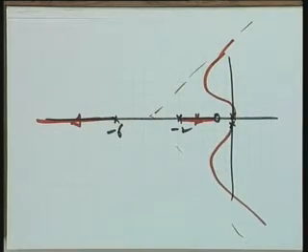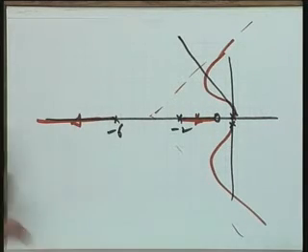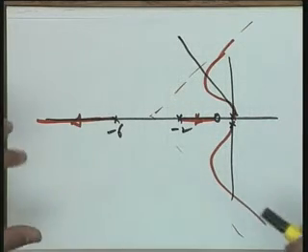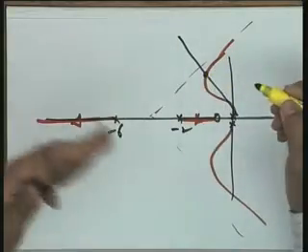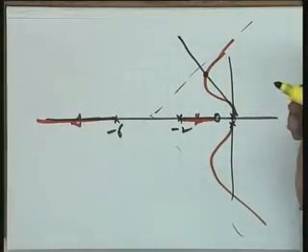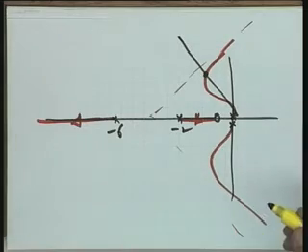So, you find that the effect of the 0 is to pull it in this direction, and hence the possibility of getting zeta equal to 0.6 has become possible. Zeta equal to 0.6, that possibility now exists, because once you are able to realize zeta equal to 0.6, you do not have to worry about KV. KV you have already done. You see, your KV is equal to infinity.